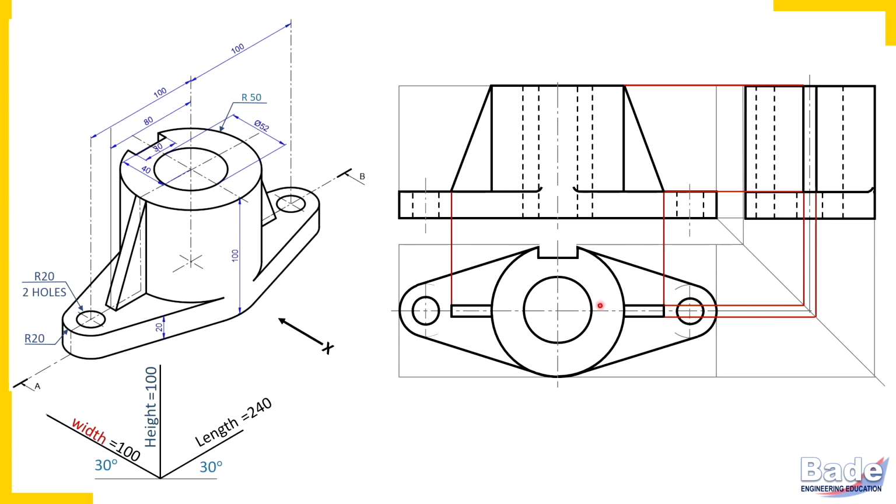these triangular plates I have transferred, I have completed in the front view, top view and side view. You can count those two plates in the front view, in the top view. But in the side view, when you are watching the object, imagine from the left side, the two triangular plates coincide, overlap.